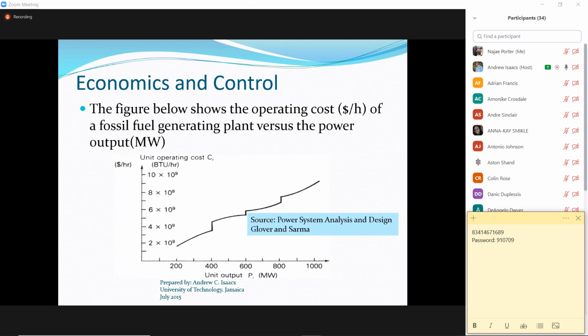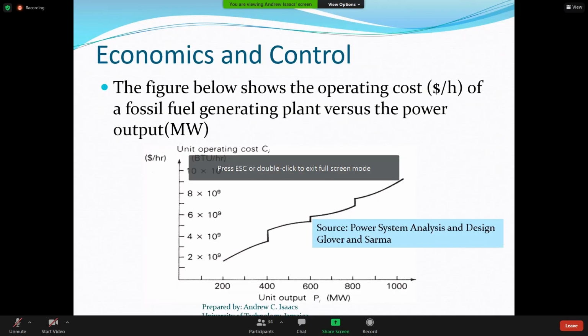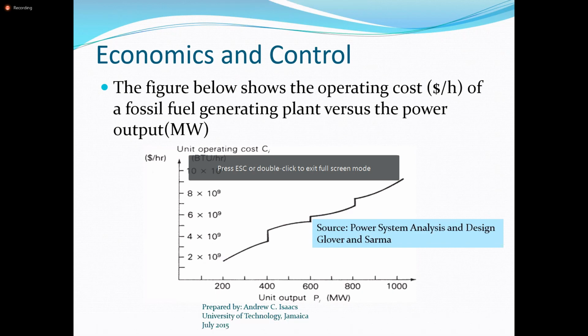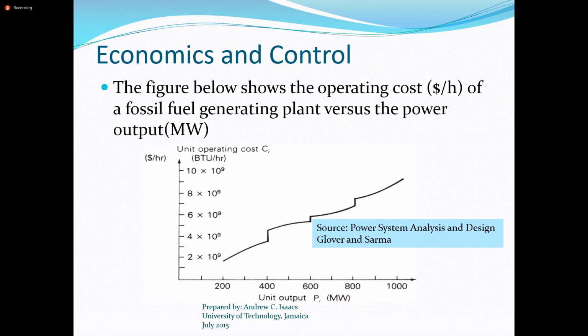Whilst we may use the same technology per se in achieving both, power factor correction is about a load or a facility where you're trying to reduce the amount of reactive power being consumed in supplying the same active power.